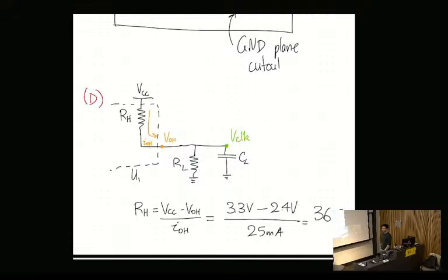Yes. I don't know why that was tripping me up. Yeah, that's correct. So it's effectively just VOH is the value when RO and CO aren't there, and then with some particular load, that voltage value will change because there's voltage division. Yep, good question. So VOH is the voltage when that particular load you're attaching isn't there, or it might be different to the load that's in the data sheet there.